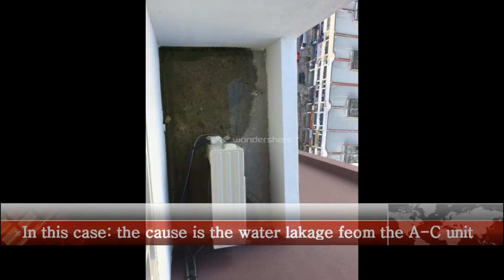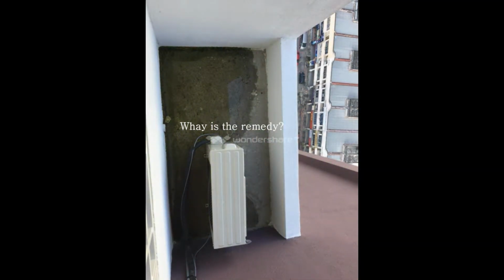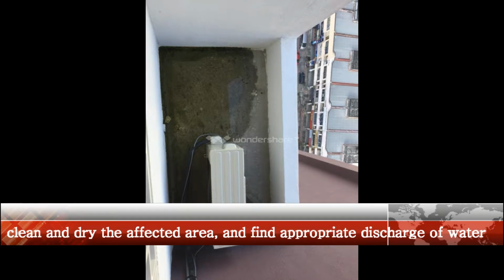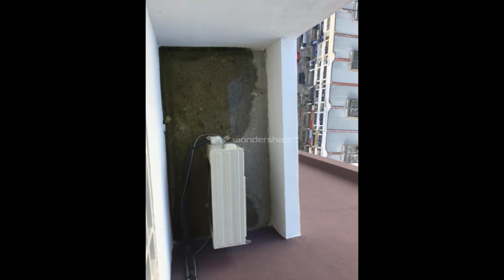In this case, the cause of the mold is the water leakage from the air conditioning unit, because we can see the air conditioning unit on the roof without a proper design of drainage. The remedy for this problem is to clean the affected area and then dehydrate it effectively and find an appropriate discharge of water that comes out of the air conditioning unit.